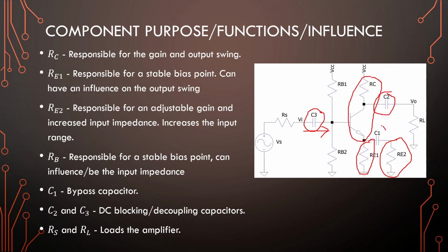And this capacitor here is just to bypass RE1 and make RE2 visible when we're dealing with the AC characteristics, and then RS and R load are either other systems or a resistive load of some sort. Okay, so every system will always have some impedance, and you can model it using this same approach.